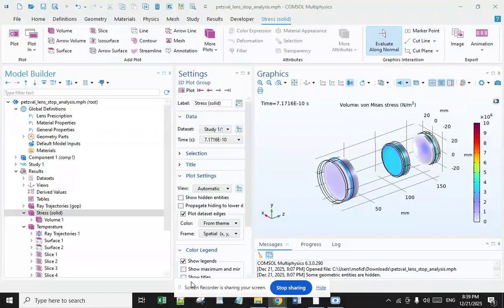This is primarily facilitated by Thermal Desktop's capabilities for mixed fidelity modeling, in which full three-dimensional meshed geometry, simplified two-dimensional shapes, and even zero-dimensional node networks can be combined within the same thermal model. This approach allows for simplification of simple geometric areas whilst retaining the required detail in areas of complex or novel geometry to attain an accurate solution.